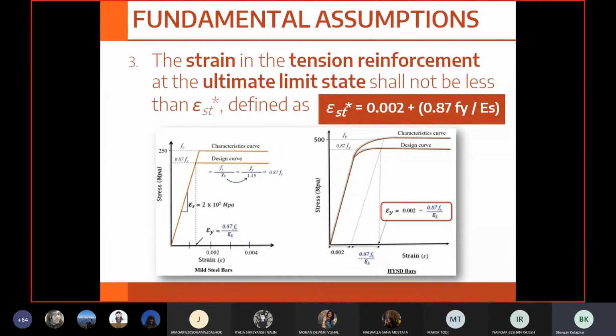To put it in simple numbers, just for your understanding, these are not real numbers. If the maximum strain that steel can take is 100, we say that the beam fails when the maximum strain in concrete is 5. The member has started failing in flexure at a value of 5.